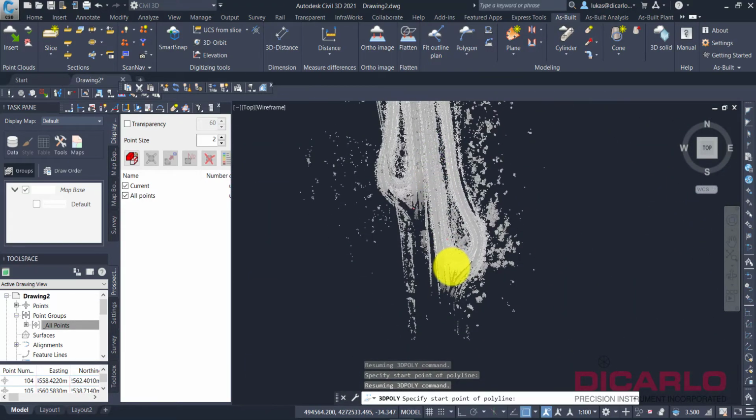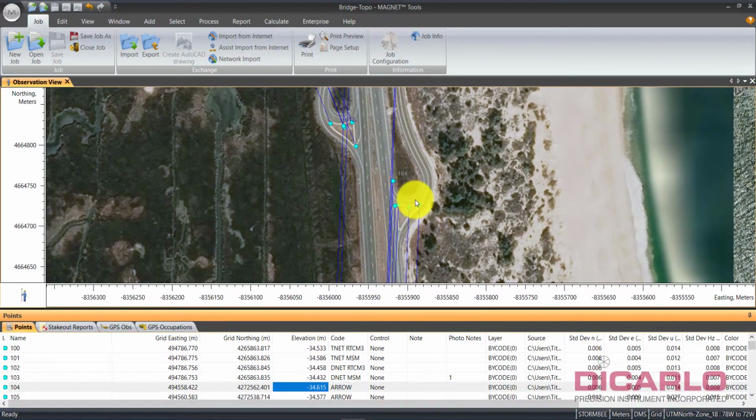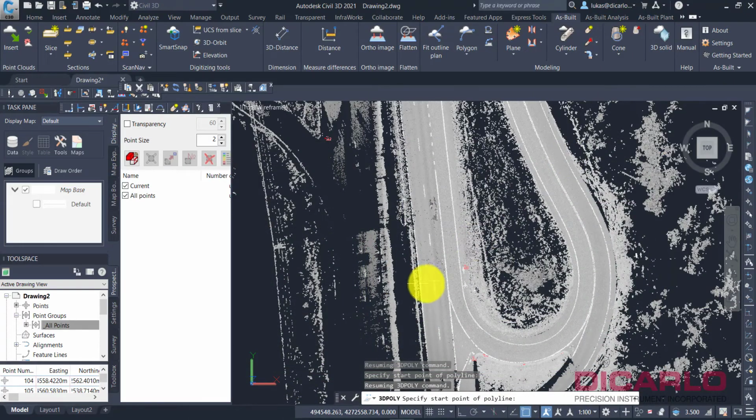But all in all, it does seem to work. And just by virtue of having one control point adjusted based on its true positions, or, well, let's assume better positions with GPS than what the BeeMobile might have done. I'm not saying that the GPS was more accurate than what the BeeMobile was able to get, but we just have to call something true. So these are my findings.